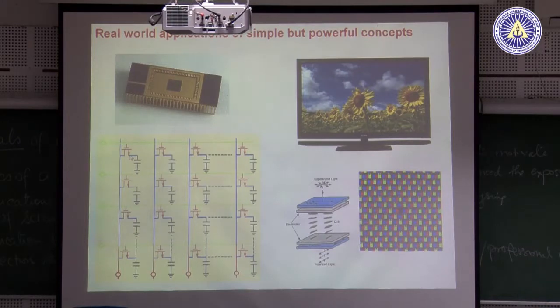The other example is this laptop, this LCD screen that you see here. If you go and look at it, the LCD screen is also like a dynamic RAM, except that in place of this capacitor, there is an LCD liquid crystal cell. It's also like a capacitor. It's a liquid crystal cell which you can make opaque or transparent depending on the voltage that you apply. And along with this liquid crystal cell, there is a transistor sitting in this particular laptop also.